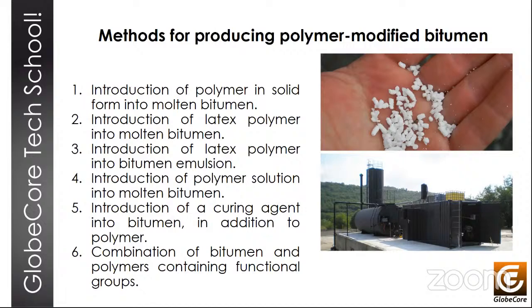In the production of modified bitumen in batches, one or more mixers are used, usually two, into which bitumen and polymers are loaded in certain quantities. And then they're pre-mixed and sent to the fine grinding mill, through which they pass the required number of times. A laboratory test is required to determine the number of passes necessary through the mill, and when that number has been reached, the mixture is considered ready for use and then can be unloaded and shipped to an asphalt plant, to a storage tank, or to a tar sprayer. Next slide, please.